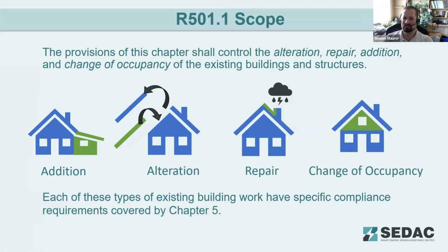As we're looking at these, additions are generally you're adding to the square foot or the surface area of the building by tacking on additional stories to the building or additional floor space. This kind of overlaps a bit with change of occupancy, where you're changing a space that's already contained within the home, such as an unfinished basement or an unconditioned attic into conditioned space. There's a bit of overlap in those requirements, and we'll go over those.